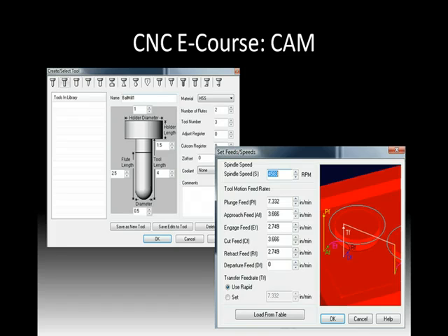On the right, you'll see a photograph where we're defining the speed. One of those speeds is the spindle speed, how fast. This happens to be for a milling machine, so how fast is that end mill turning? How fast are we going to plunge into it? These are all things that the CNC machine needs to know, and we need to define them before we go out there. Part of that's just a safety factor as well.